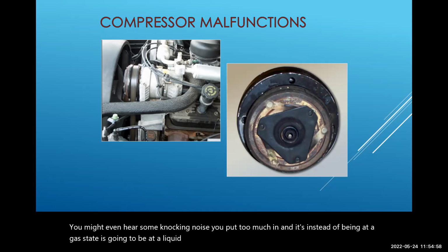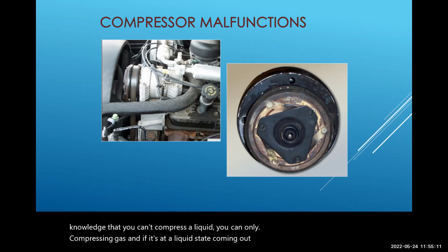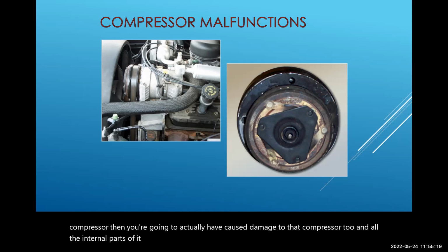From general mechanical knowledge, you can't compress a liquid. You can only compress a gas. And if it's at a liquid state coming out of the evaporator going into the compressor, then you're going to cause damage to that compressor and all the internal parts of it also.